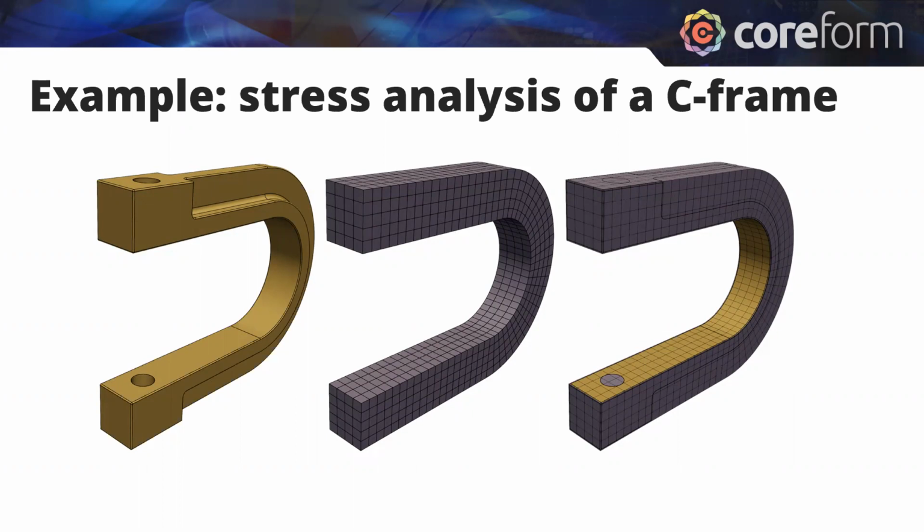In the US there's an organization called OSHA that specifies that you can't have these sharp edges that could cut someone. So they put those fillets in, and that's now in your design model. Clearly, I don't want to mesh those. If I care about whether or not, if I load this, am I going to fail at the inner part of this bend, I would defeature those away. But again, that's part of that workflow cost that we pay.